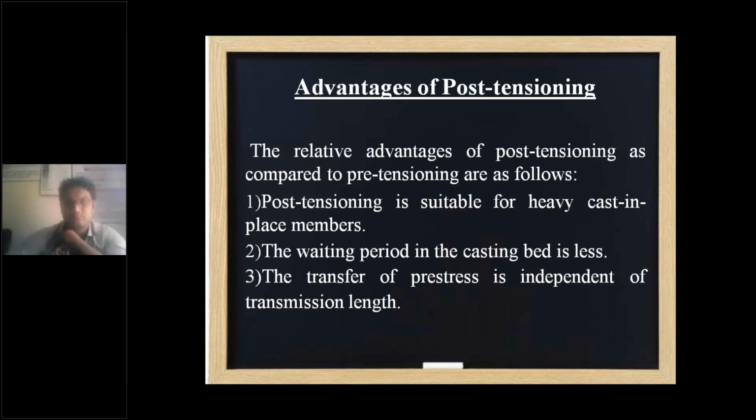And let's see the advantages of post tensioning. There are a lot of advantages compared with pre tensioning. The first one is that post tensioning is suitable for heavy cast in situ members, very important, like girders in the bridges. They are all very heavy, and they are supposed to be cast in situ. Whatever girder I showed you in the video, they are all cast in situ.